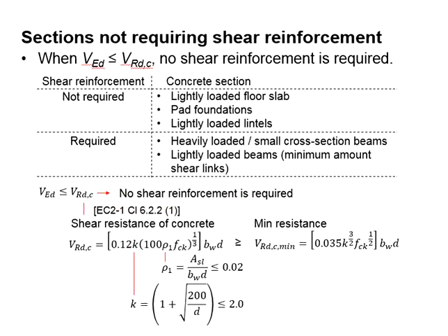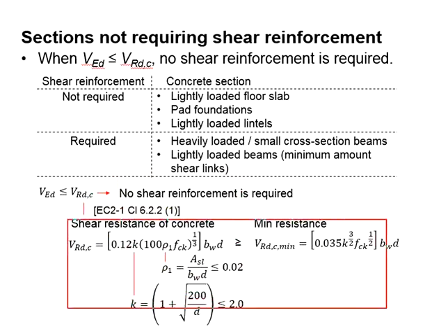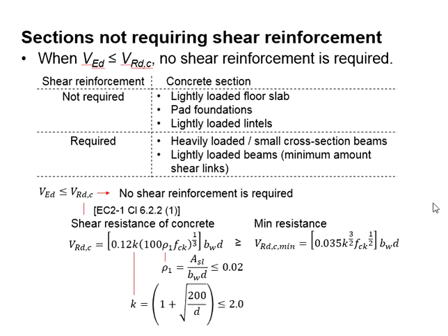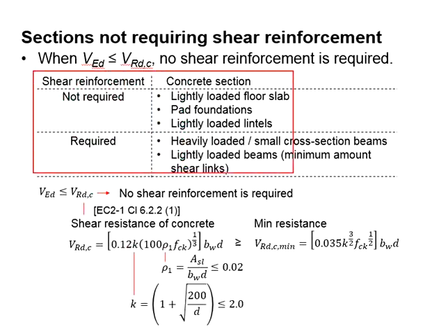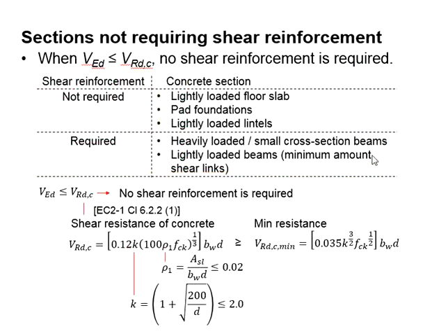In other words, these equations are not meant to design the shear reinforcement. They are used to determine whether the shear reinforcement is required. Now, these are the conditions where the shear reinforcements are required and not required.